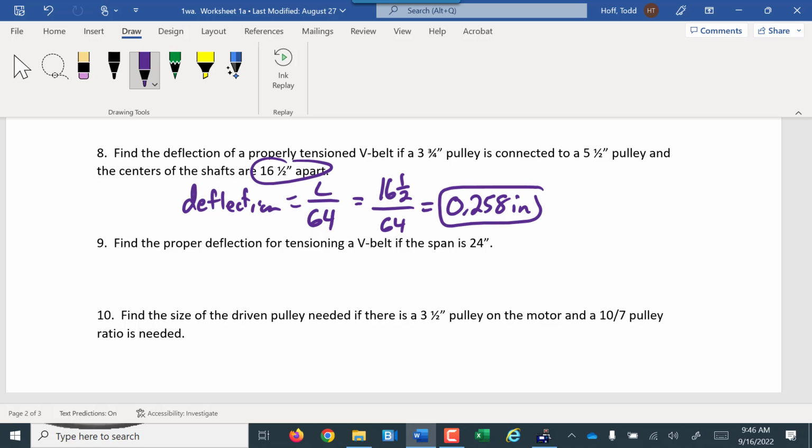So when you press on that belt, do you guys know what we're saying when we say deflection? Yeah. Just press on the belt with, I've never actually seen the exact amount of force. I'm just not going to lean on it, but generally the belt, even if you press really hard, it shouldn't go much more than a 1/4 inch away from its normal path.